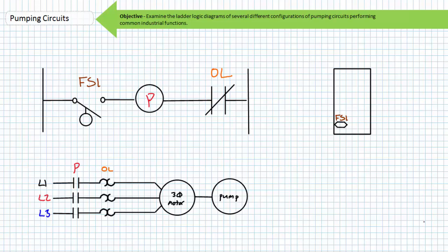Pause the lecture often and see if you can figure out how the system would respond to certain input conditions. Draw pictures, take notes. As you'll recall, magnetic motor starters are divided into 2 general categories: 2-wire and 3-wire control circuits. 2-wire circuits are ordinarily characterized by automatic switches like temperature, float, or pressure switches and are suited for applications in which the automatic starting of the motor would not present a safety hazard.